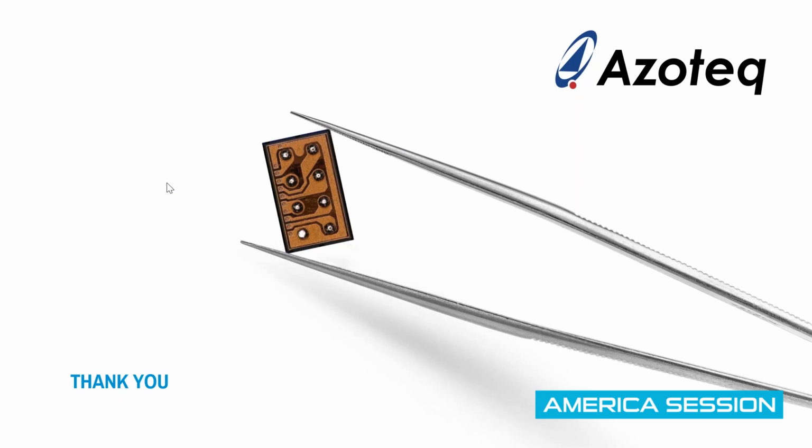So typically we would be sampling at 10 milliseconds or so. After a certain period of non-activity, let's say 5 seconds or 10 seconds, then we can go into a low power mode where we sample at a reduced frequency, either 100 Hertz or 25 Hertz, depending on what your requirement is, how quick it should wake up.